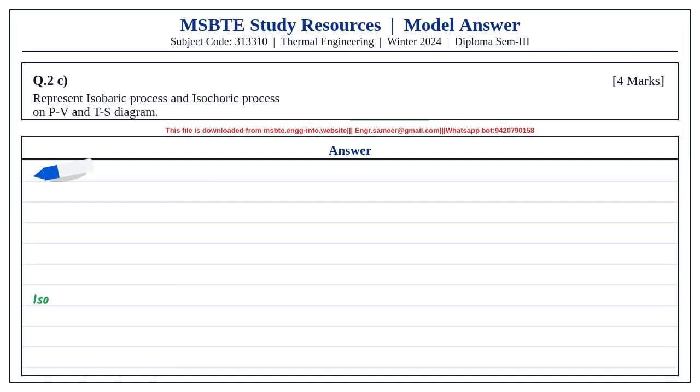Question 6b. Classify heat exchangers and state their applications. Heat exchangers are classified according to nature of heat exchange as direct contact type and indirect contact type.